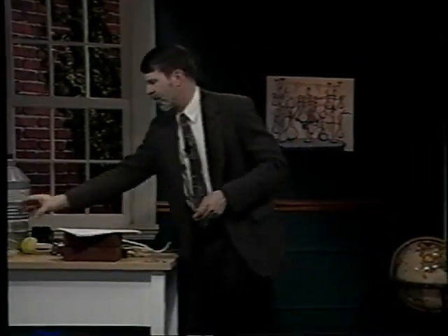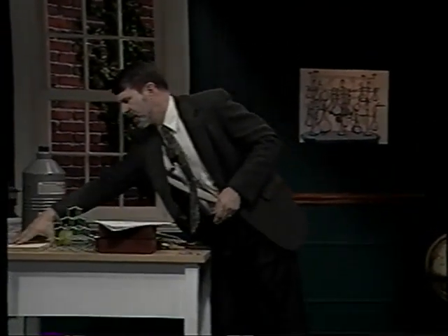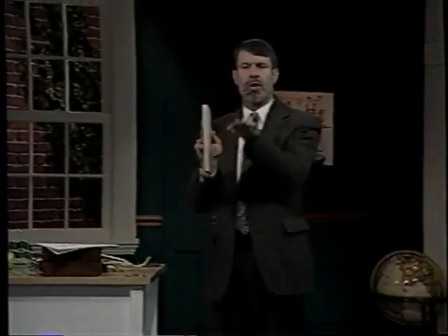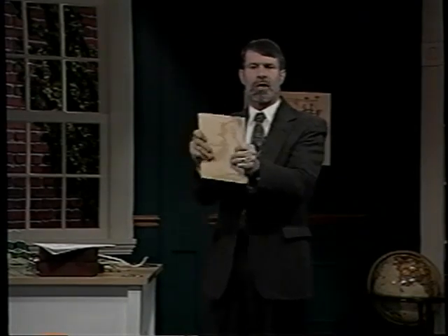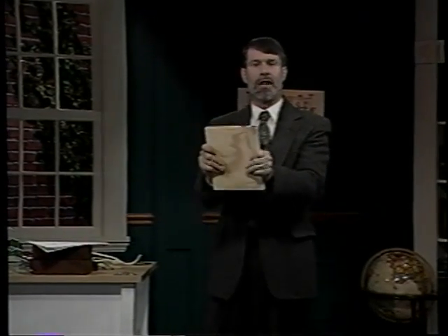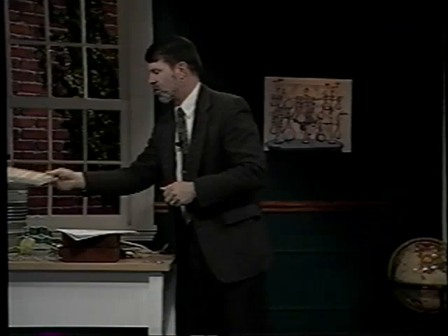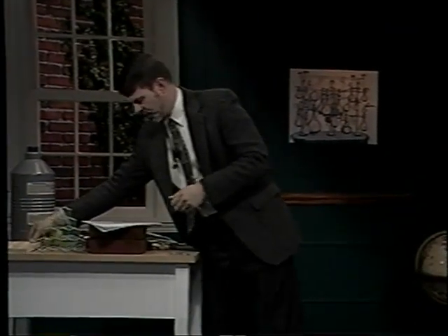This is why composite materials are now being used extensively in earthquake-prone areas. We talked about reinforced concrete with steel rods going up through concrete. That adds shear strength. Also, it's very simple in a wood building just to apply plywood. If you nail plywood sheets in between the framing, the plywood, which has layers of wood going in opposite grains, is extremely strong under shear and therefore resists earthquake damage much, much better than a normal frame building would.